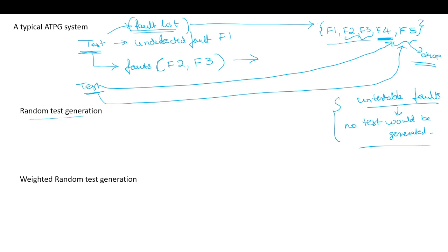Another method to generate the test pattern is random pattern generation. Random patterns can detect up to 70 to 75% of the faults. It's the simplest form, we just need to generate the random patterns. If n tests are randomly generated, the probability that T can detect all structural faults in a given circuit depends on the circuit.